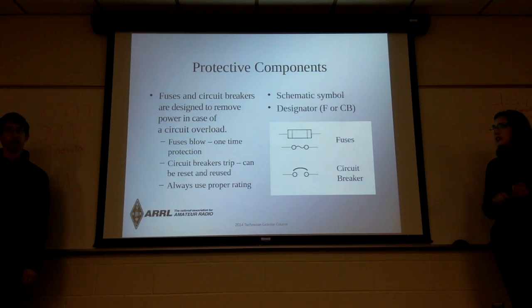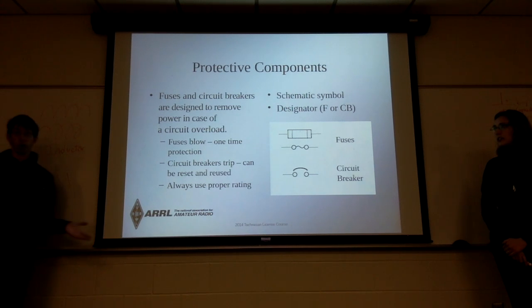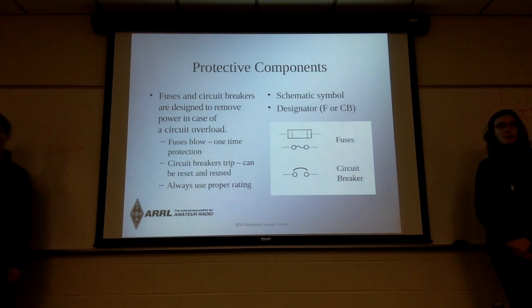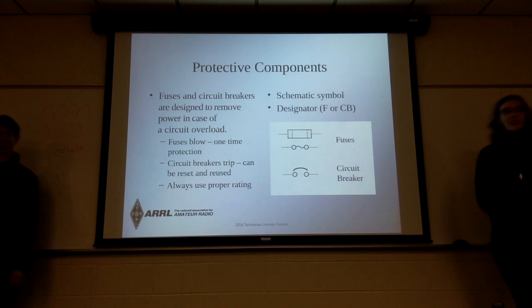If you try and stick a paper clip in where a fuse goes, it'll work. I almost guarantee it'll work. I got 16 cents out of a fuse panel. Oh gosh. So yes, some people use coins. You can use coins as well. And pennies and silver dimes really conduct electricity well. You can burn down a house that way.